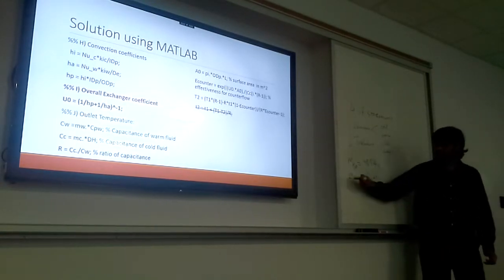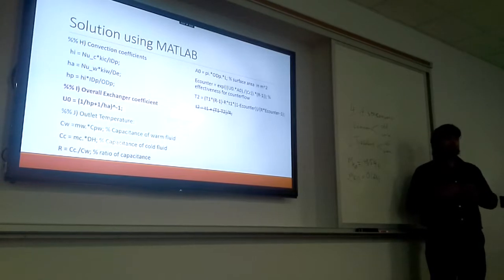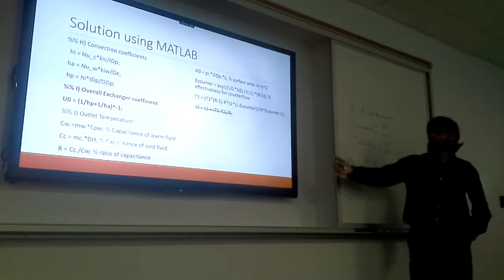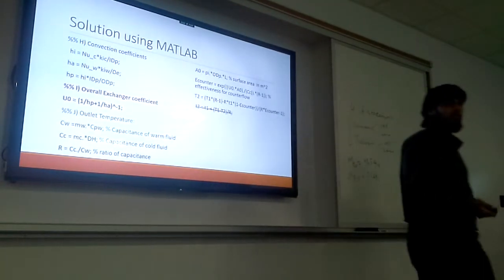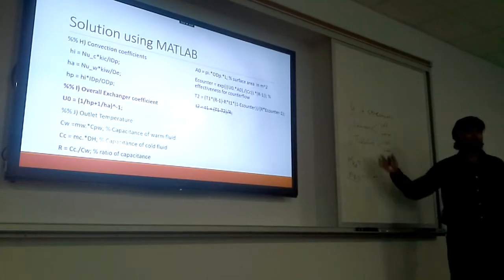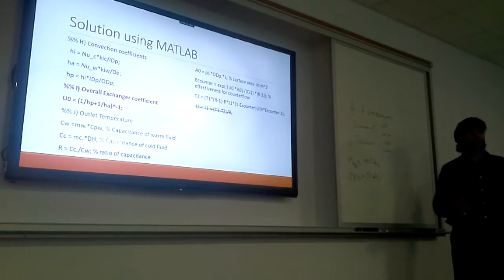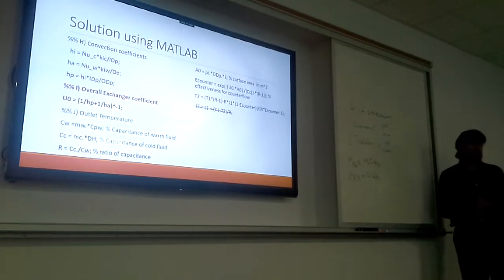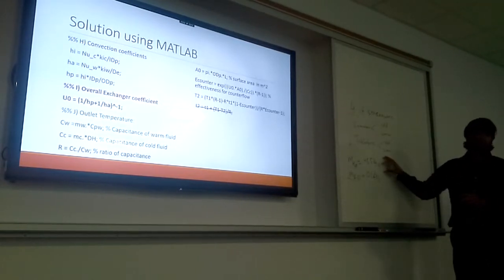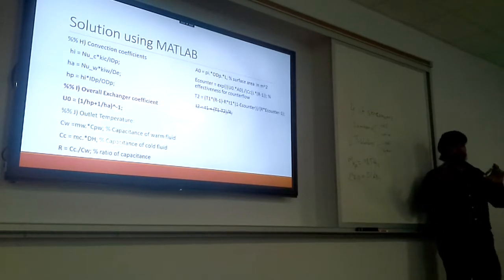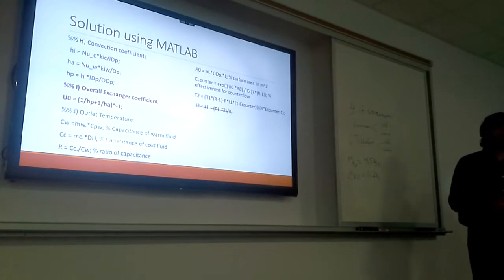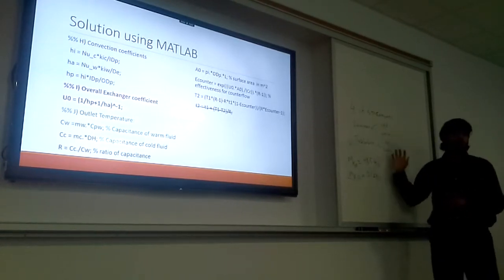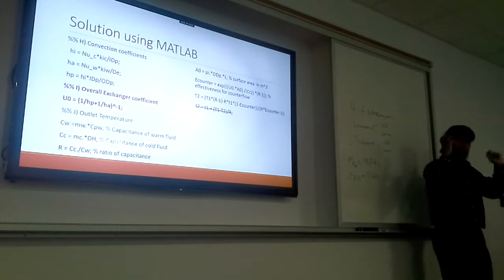So even if the refrigerant has a high heat capacity, because of the flow rate, the capacity goes down compared to the water. I think that's a big difference. So the energy that's transferred to the water is significant, but it doesn't affect the temperature as much because of the overall capacity the water has, due to the large amount of fluid going through. Okay? This is something to keep in mind when you do analysis.